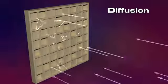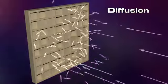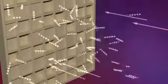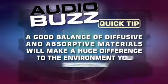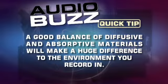With diffusion, the idea is to keep sound waves from grouping up in areas throughout the room. Common types of diffusion panels are constructed out of wood and look like grids made up of squares or similar shapes. The sound hits the grid, and as a result, it breaks up the sound wave. A good balance of diffusive and absorptive materials will make a huge difference to the environment you record in.